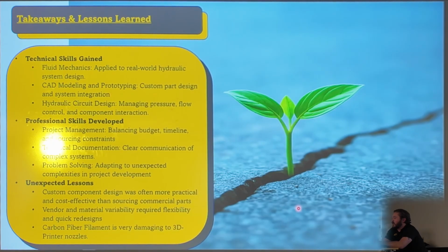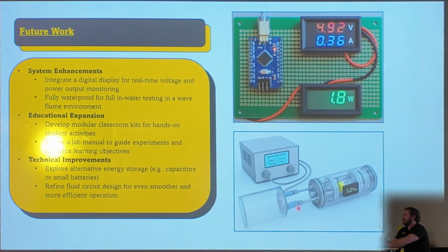And then another unexpected lesson is that carbon fiber infused filament is very damaging to 3D printer nozzles. After just a few prints, it had essentially destroyed the whole nozzle on the 3D printer. That's good to know. For future work, I really want to look into advancing my project in a way that